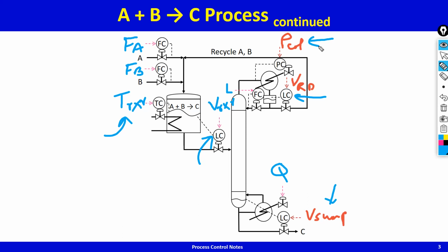Whatever steam rate that we're putting in, according to that we'll have a product. Of course its quality will be whatever it is, we are not doing any quality control, so the product will be whatever it is. And similarly the amount of impurity in the top will be whatever it is, because reflux is fixed.